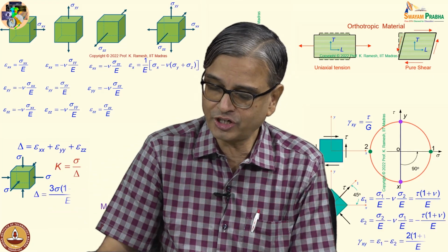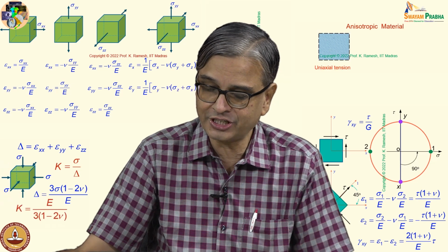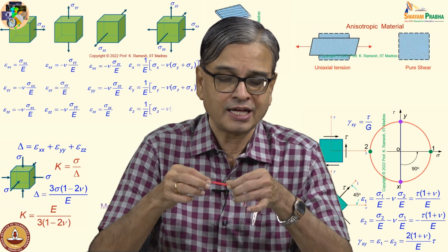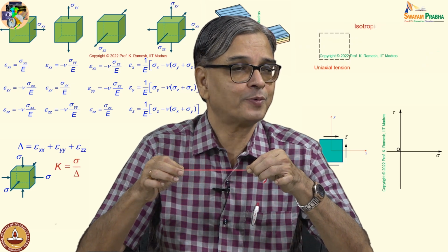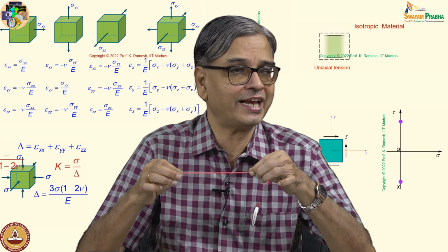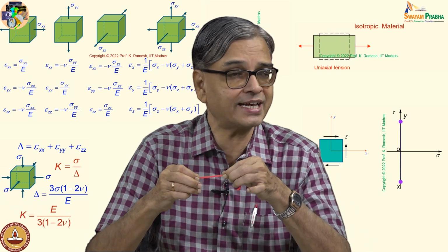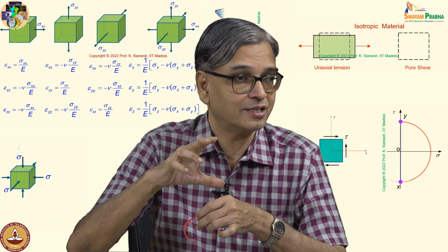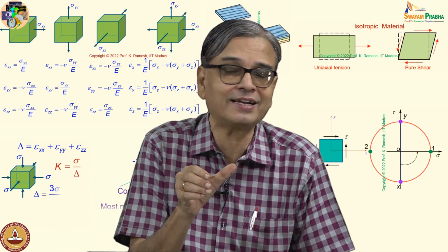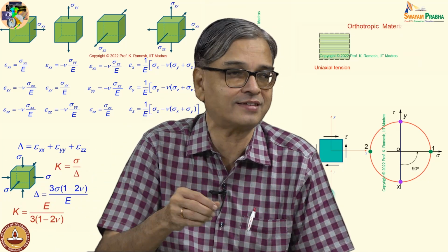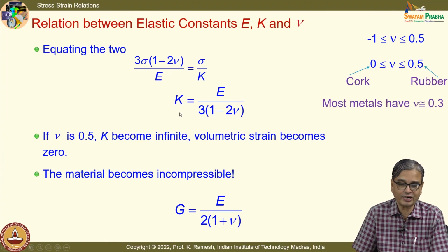Normally, when you look at Poisson ratio, what we imagine is that when I stretch, the lateral part gets opposite strain. When I stretch it, it gets shrunk. When I compress it, it can bulge out. So, if you are sealing a bottle, when you are applying a compressive force, if it bulges out, it will be difficult for you to insert it. That is one of the advantages.